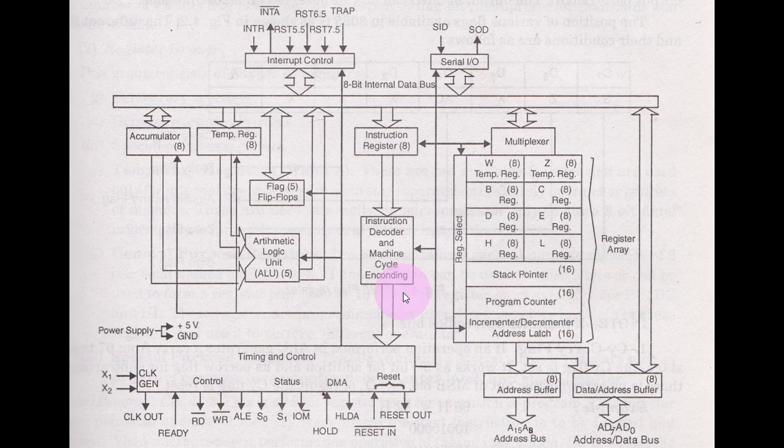In the PDF, you had mnemonics, its opcode, its hexadecimal code, and its decimal code. Whenever an instruction is read from the external memory through the data bus and address lines, that instruction is directly put through the instruction register into the instruction decoder. The instruction decoder clearly knows that if a hexadecimal equivalent this much comes, then what it means.